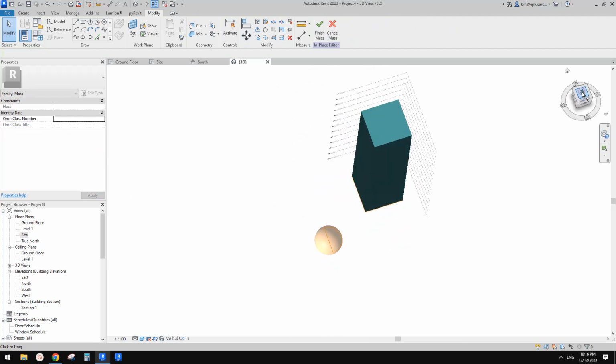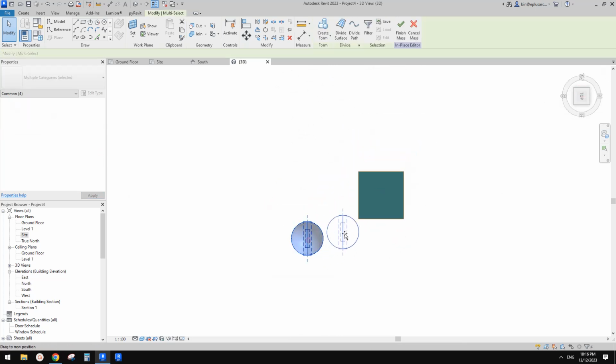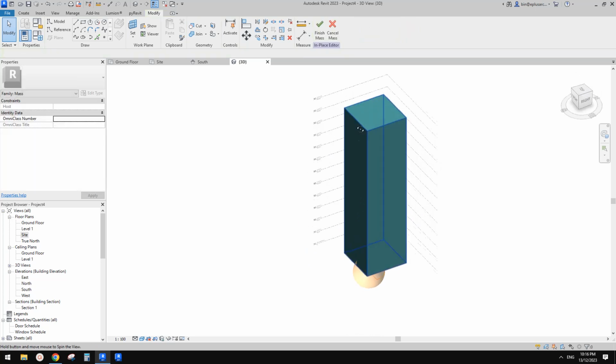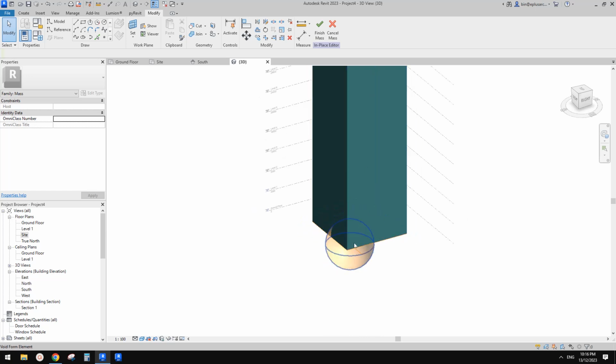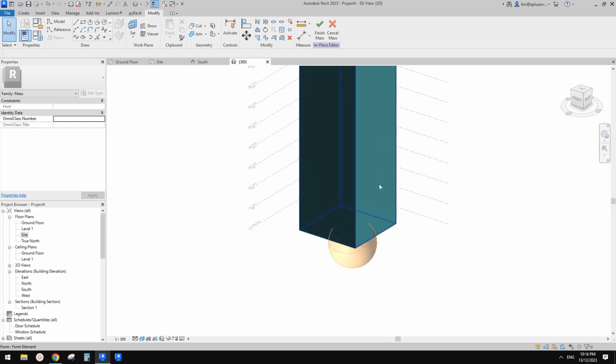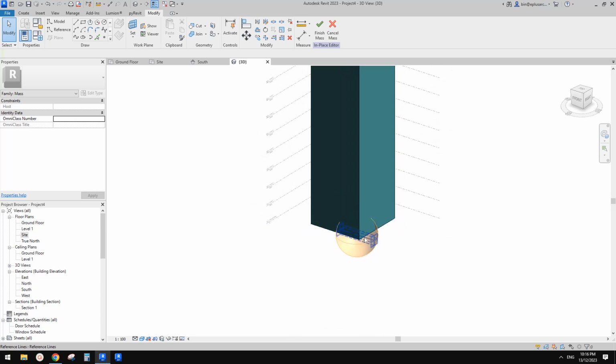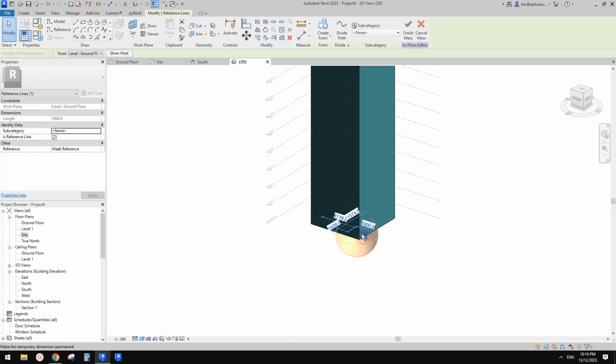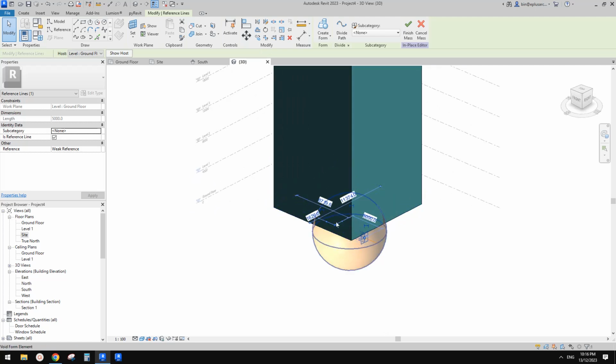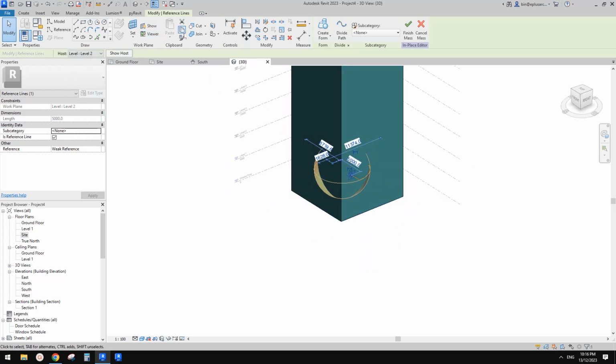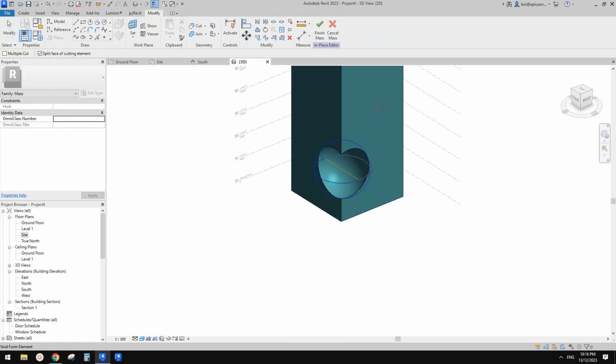And then we can just go to the top. So we can just move it to, cut this. So for example, here. And then maybe to change the level, change the height of this void, we need to check tab select this void. Tab select until you pick this shorter reference line, and then we can change this to a different level. So for example, I'll change it to level 2, and then we can use cut geometry and click and click.